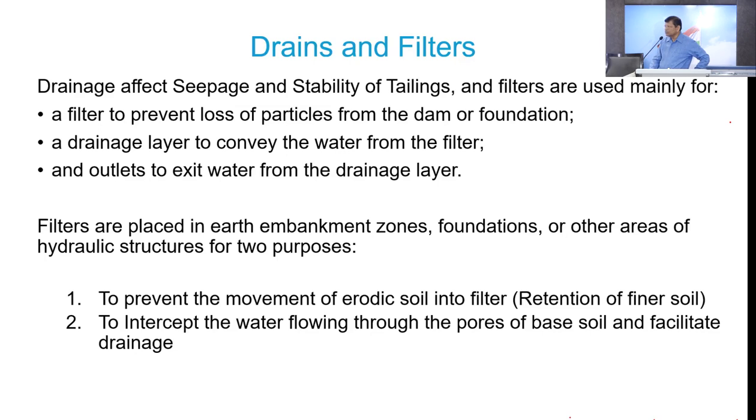So the main two aspects of the filter. One is we are not allowing any fines particles to go through. So that's the first thing: retaining of the fines particles, because these fines particles are causing all the havoc. If you retain that, then you are good. And the second thing is, you allow the water to go, because filter is like a drainage. So two things we have to check.